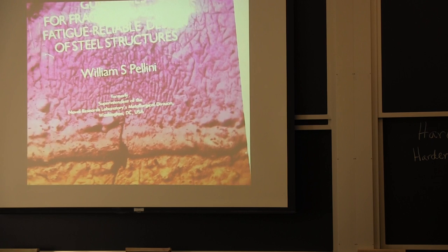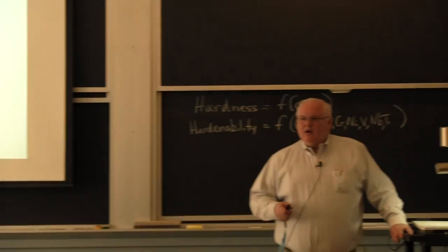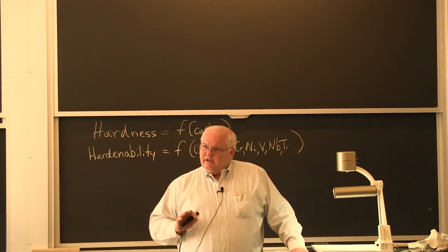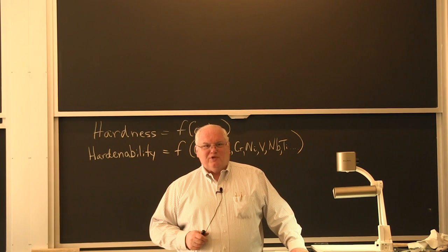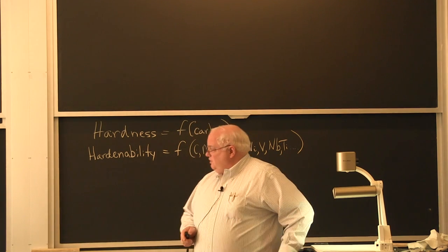So arc strikes may be cosmetically unappealing, but they can actually be harmful, and so many of the codes will require that you grind off the arc strikes. Okay? And you don't like welders who go around hitting the electrode where they're not supposed to, when the lights aren't on, okay, when the arc's not going, so far as that goes.